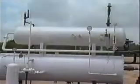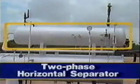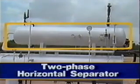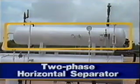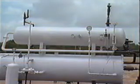Our next separator example is very similar to this one, except the cylinder has been positioned horizontally. So let's go take a look at it. This horizontal placement increases the liquid surface area, which, in turn, increases the efficiency of the vessel for gas removal. That's why these 2-phase horizontal separators are used for processing well streams with large volumes of gas.